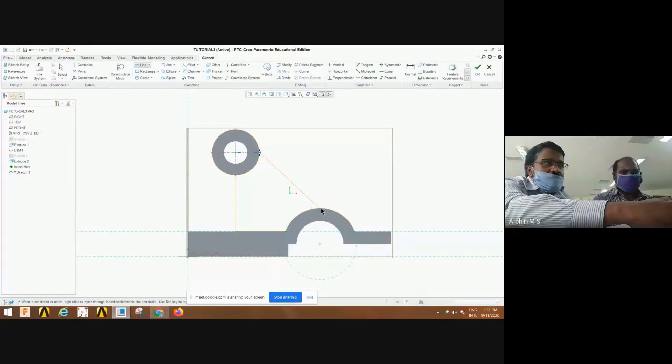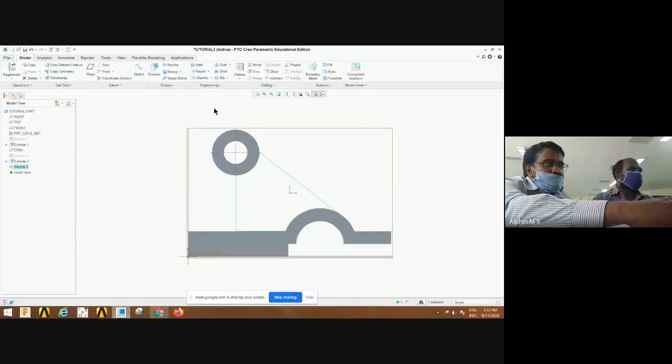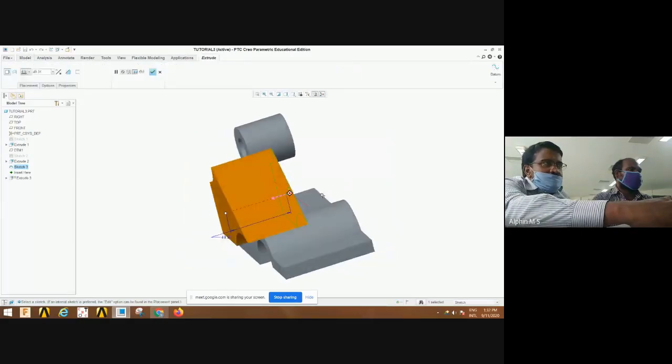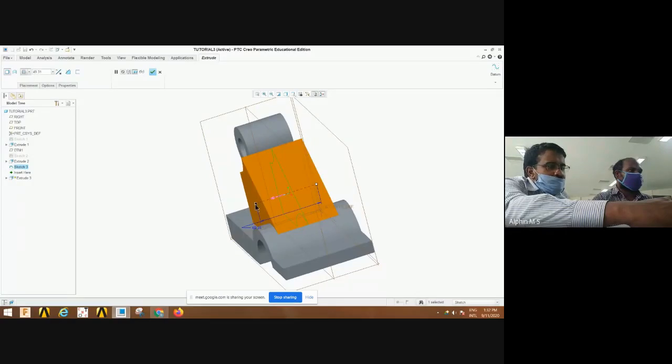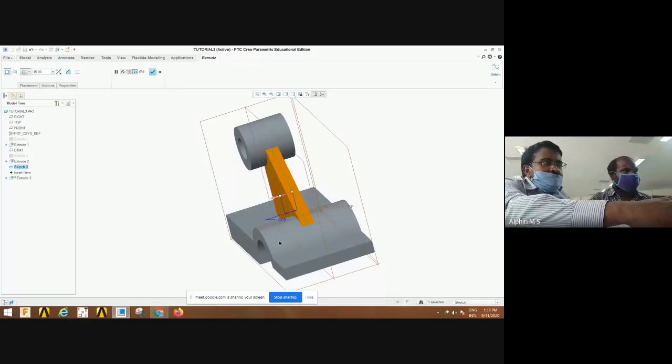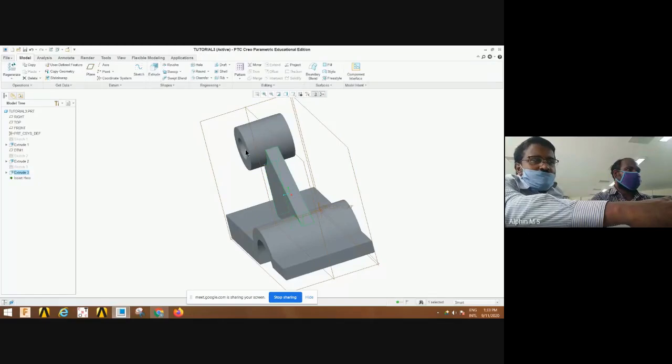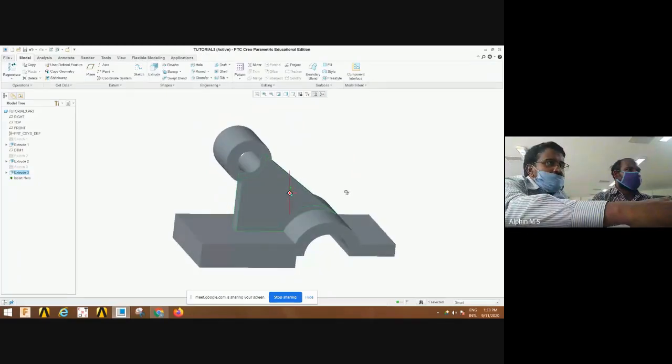So now we are constructing the rib, the supporting rib for the cylinder, that circular part. We know the slope is extracted from the tangent of this semicircle to the center of that. Then we got the extruded thing. But we have to parametrically revise the rib geometry. It is 10 here. So now it is correct. We have made it 10. Now the rib is ready.